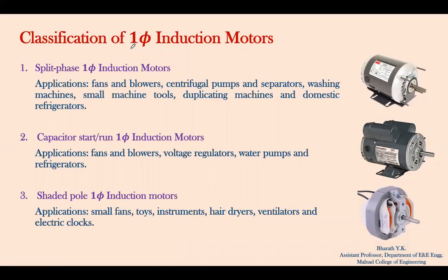Now coming to the classification of single phase induction motors. So basically there are three types: split phase single phase induction motors, capacitor start or capacitor run single phase induction motors, and shaded pole single phase induction motors. Split phase single phase induction motors are used in fans and blowers, centrifugal pumps, separators, washing machines, small machine tools, duplicating machines, and domestic refrigerators.